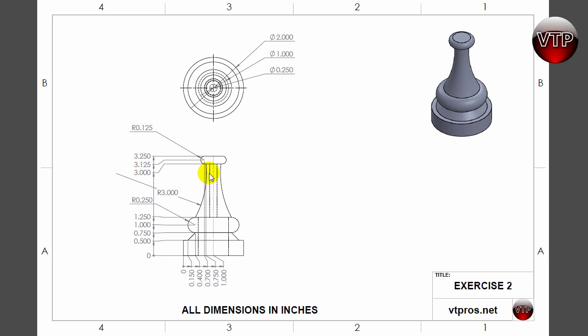And then from here to here, I'm going to be placing a point up here, which is going to be y equal 3, and x is going to be equal to 0.7 or 0.75, and then connecting them by this radius. And I'll show you how to create this radius right here. Okay? And then we'll create this slot right here all the way up to here. Once we have this all done, that's when we know our entire part geometry is created.